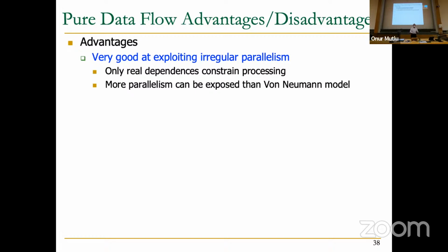Because if your entire program is Dataflow, and you somehow put it onto a Dataflow machine, somewhat like out-of-order execution but without the von Neumann parts, then that machine can actually be extremely powerful. Think about a huge Dataflow graph that you put in, where thousands of instructions can be executed in parallel at any point in time, right? But of course, you need to provide the hardware resources to execute those instructions as well. You're not limited by sequential execution at all.